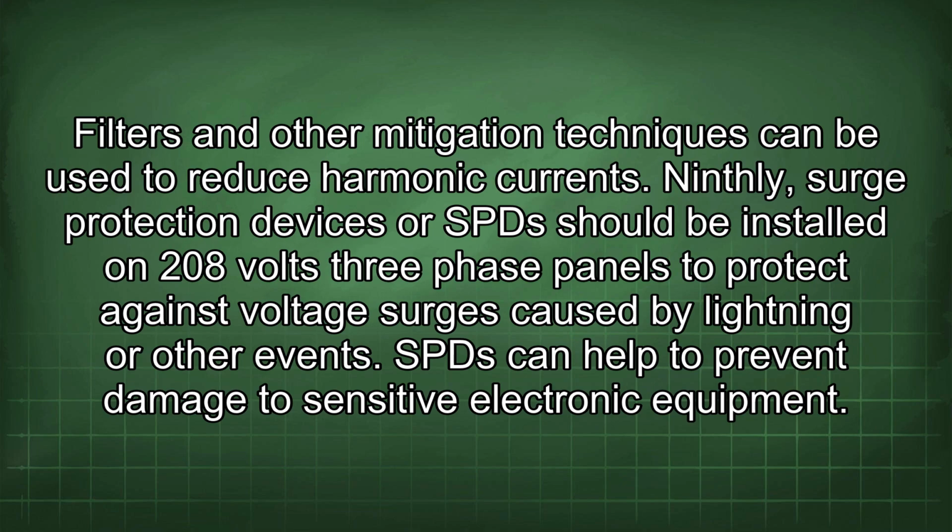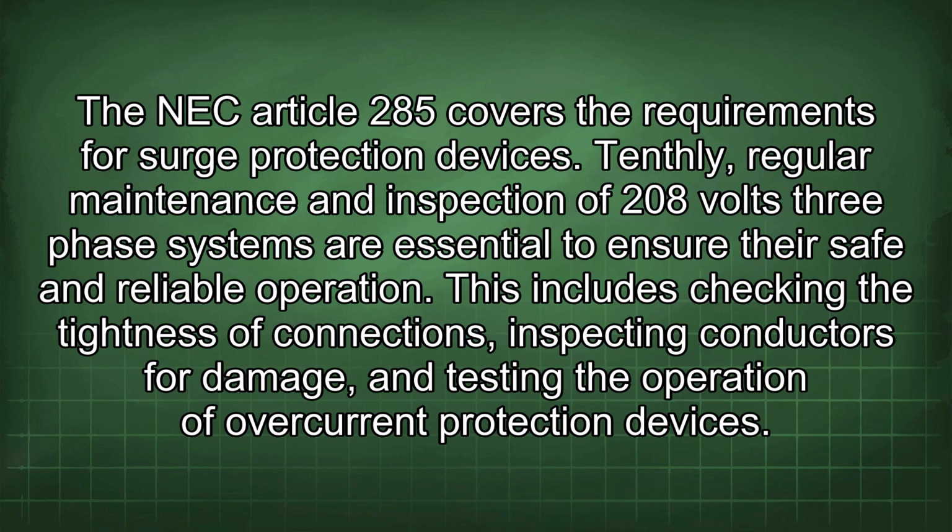Ninthly, surge protection devices or SPD should be installed on 208 volts three-phase panels to protect against voltage surges caused by lightning or other events. SPD can help to prevent damage to sensitive electronic equipment. The NEC Article 285 covers the requirements for surge protection devices.